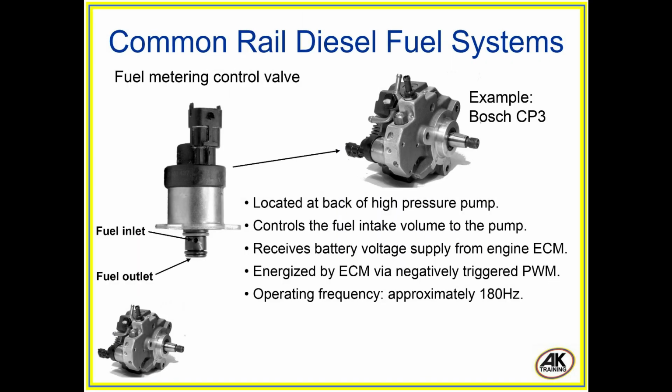Fuel metering control valve. Located at back of high-pressure pump. Controls the fuel intake volume to the pump. Receives battery voltage supply from engine ECM. Energized by ECM via negatively triggered PWM. Operating frequency, approximately 180 Hz.